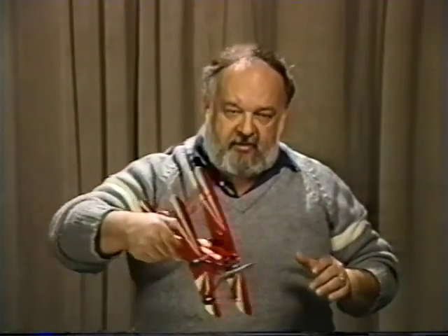There are some reports that talk about how to build in spiral stability, and that is a function of dihedral, length of the tail, and size of the tail. Because you want the airplane to be stable this way, but the dynamic end of it is going off into a spiral. Model airplanes are built so they have spiral stability, and most airplanes that we fly today are not spirally stable. If you take an airplane, put it into a bank, and let go of the controls, it'll gradually tighten up its turn and get into a real tight spiral.